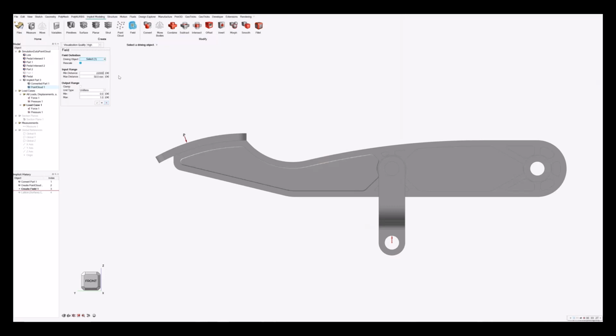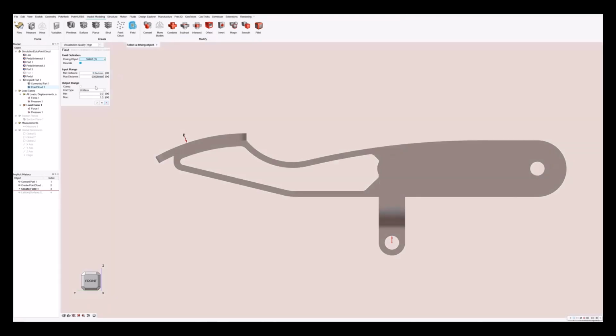We have a units mismatch, so I'm multiplying by 1,000 to get into the correct scale for the conversion. Once this is done, I specify that the output range will be in percentage, and I'll clamp the values so they don't go above or below 0 or 100%. And I'm going to put some preliminary values for the relative density, let's say 50 and 75%, and accept this.